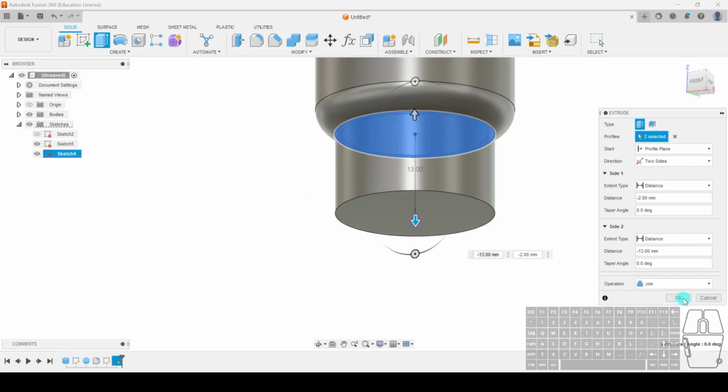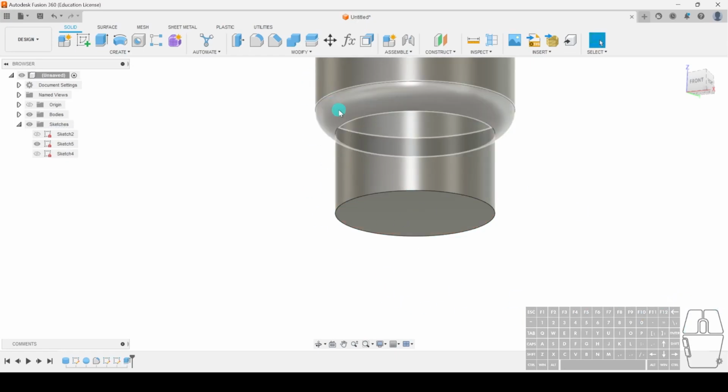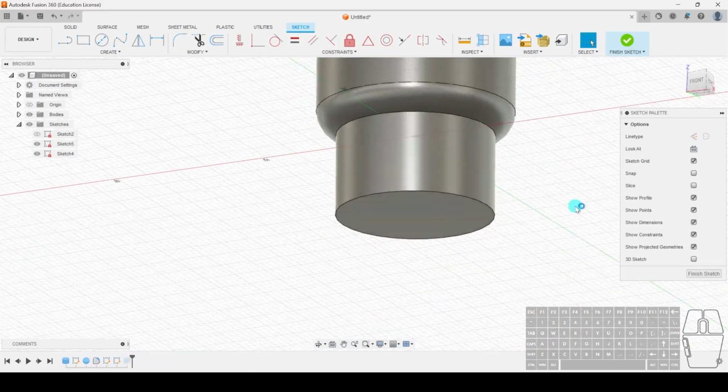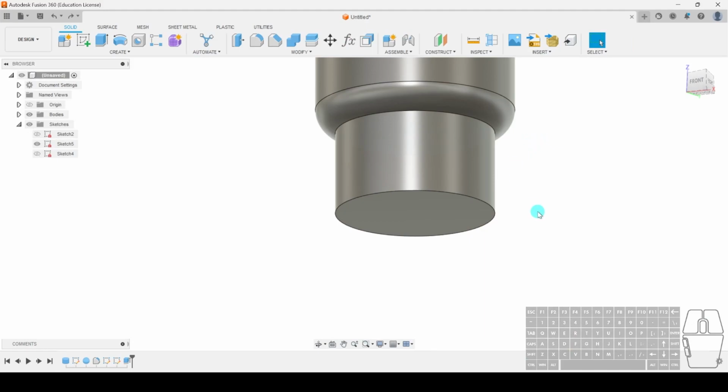I'm not going to care about the distance for now, you can see that our fillet is still connected to the cylinder, but it is appropriately dimensioned to, in this case, 24, was it? Yeah, 24. So it's just a helpful tool that if you're making threads, make sure that the dimension is correct. And it might be better to make a new sketch and a new cylinder, because especially if you need to change your light bulb, say you need to increase the housing size, or you need to change the fillet with your user parameters, then if everything is constrained, if everything is related to one another, you're going to find that your cylinder changes as well.